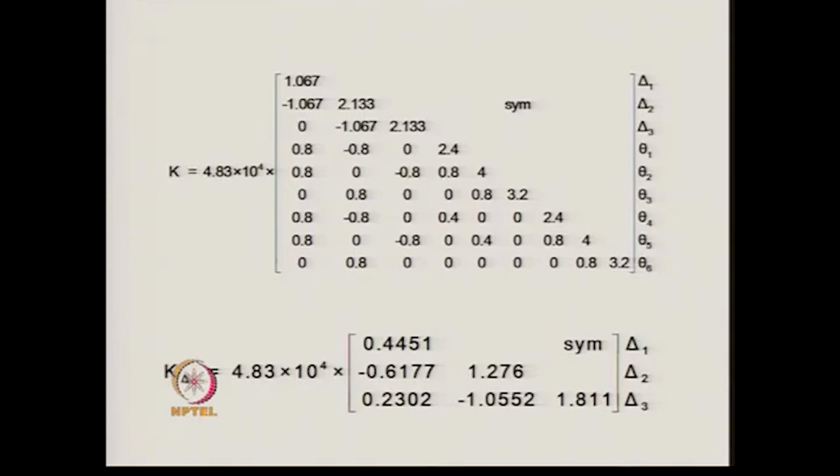When the system is weak beam strong column, then for both 2D and 3D frames the problem becomes the same, because the beams can undergo only one-way bending.